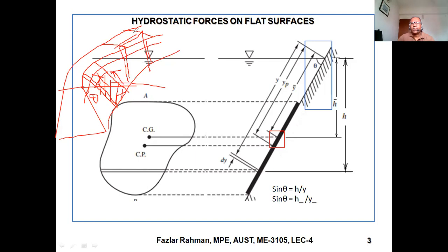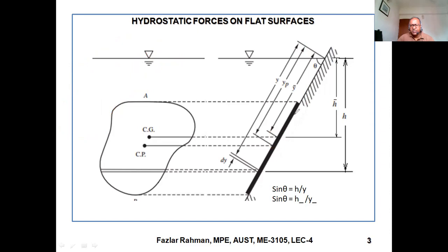Okay. So this is the inclined surface of the dam that I showed you before. And this is the plate. And this much is the inclined length along the dam surface. And this arbitrary shape is AB. This is A, this is B. So obviously it has an area of this plate. It has a location of CG that is showing over here. And also it has a pressure center. That means the resultant pressure is working through a point, and it is experiencing force and pressure.